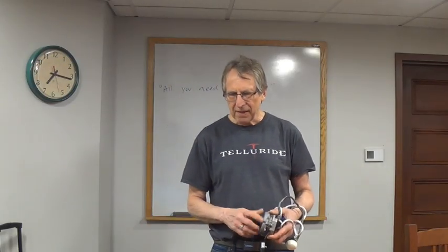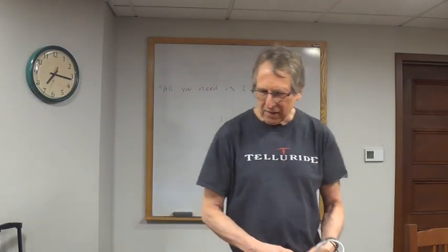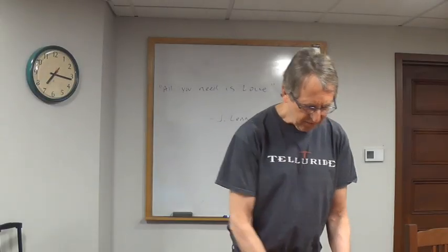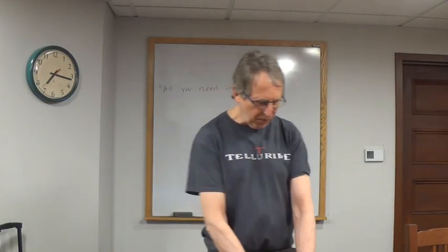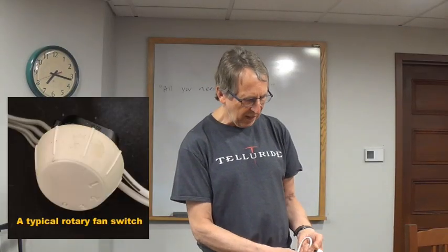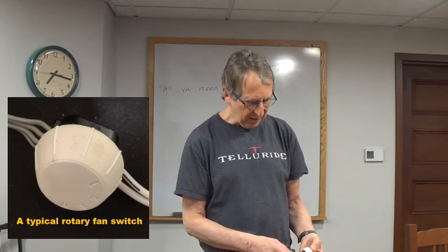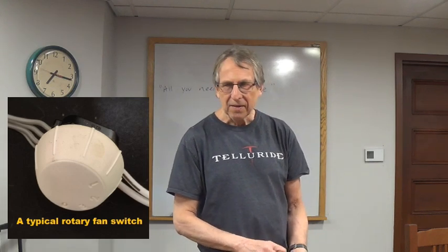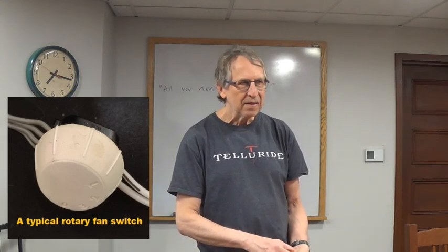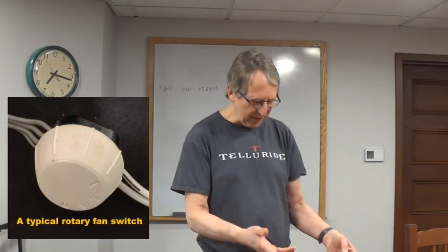All right, then the next thing, once you realize the fan turns okay, like this one turns pretty smoothly, a lot of times the problem's not in the motor, but in the switch. There have been a lot of switches where I've ended up replacing them because a lot of times when you turn them, they feel kind of crunchy. That usually means there's some wear, so once again, nothing to do with magnetic fields.